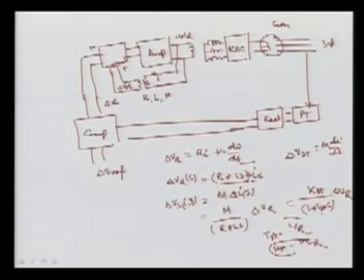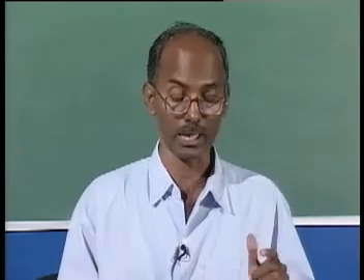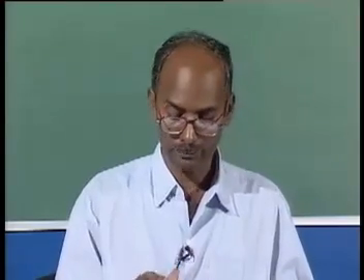of the system. So in total, this is your feedback, meaning we can improve the stability either using the series or the shunt, or with what is called the feedback, and here we are using positive feedback, and it will improve. You can now put this in the feedback and analyze it. By changing the values of M and R, we can change the feedback, because this gain is directly related to M upon R. So M, the mutual coupling, we can change by arranging the winding in such a way. R is the resistance, and it is always very small, because if you put in more resistance there will be huge loss. So this is your feedback controller.